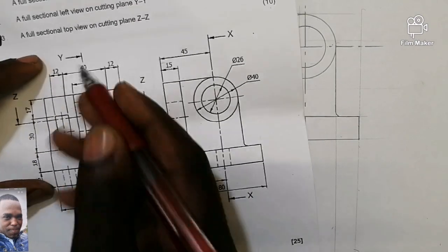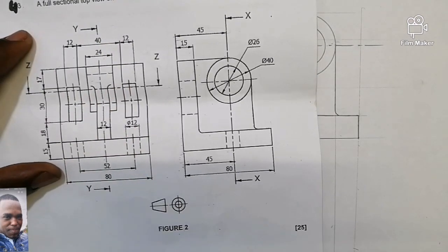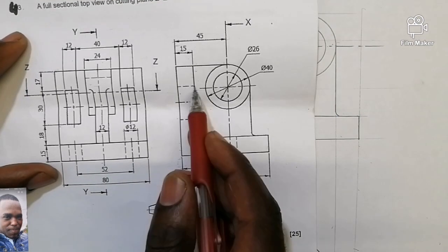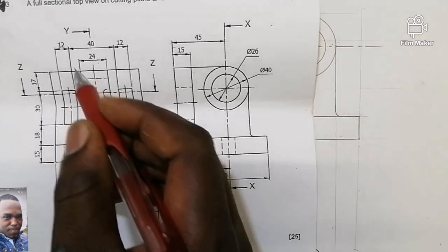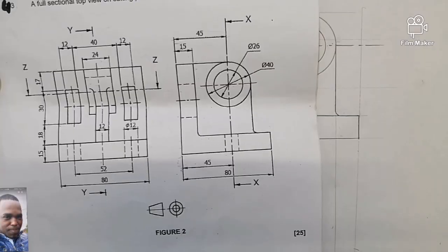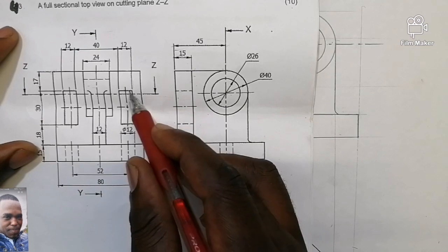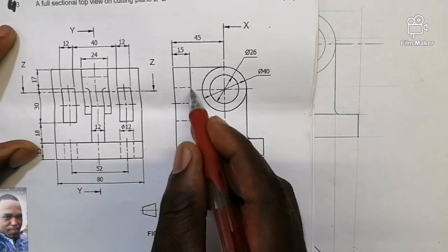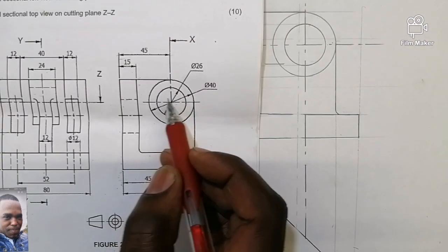Are we together? So when we are taking a closer look at your cutting plane YY, what is going to be in sectioning there? We are having these hidden details. So these hidden details, are they going to be affected? Yes, they are going to be affected, because this hidden detail, they are going to be affected. How? They will disappear. So you don't even have to show them, because these hidden details are actually showing you this. Do you see that there are two? The other one is before the cutting plane, the other one is after the cutting plane. So they are going to be removed. So you don't even have to draw them there.